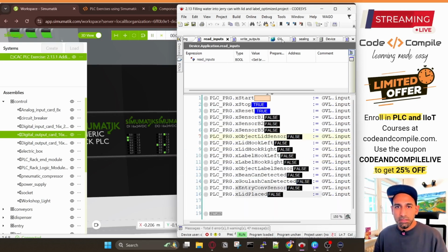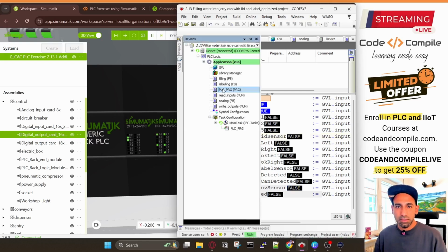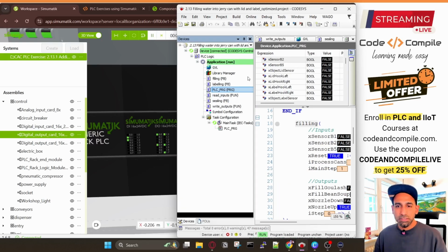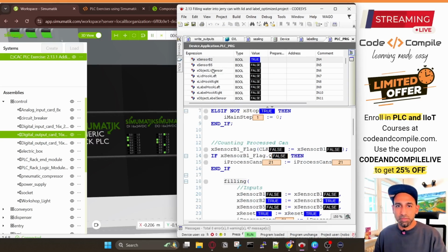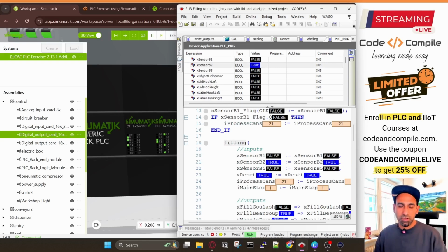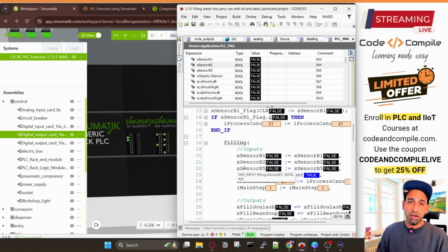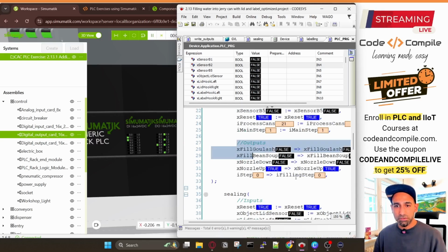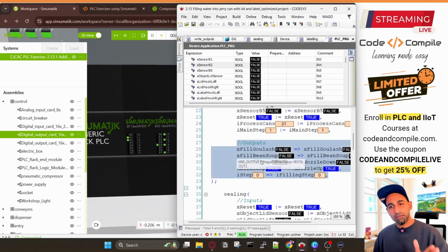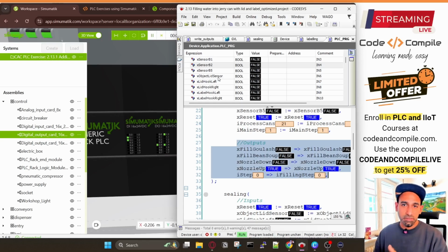Okay. And then in the PLC program, I am calling these function blocks and I'm passing these variables, which were my inputs, to these function blocks. So these function blocks also have variables. So first I'm reading the global variables to my PLC local variables, and these local variables are passing the sensor data to the function block. And this function block will execute based on these signals, which are sent by this input. And then it generates some outputs. So the function block gives me some outputs, which is over here. And these outputs are given back to my PLC variables in the PLC program.